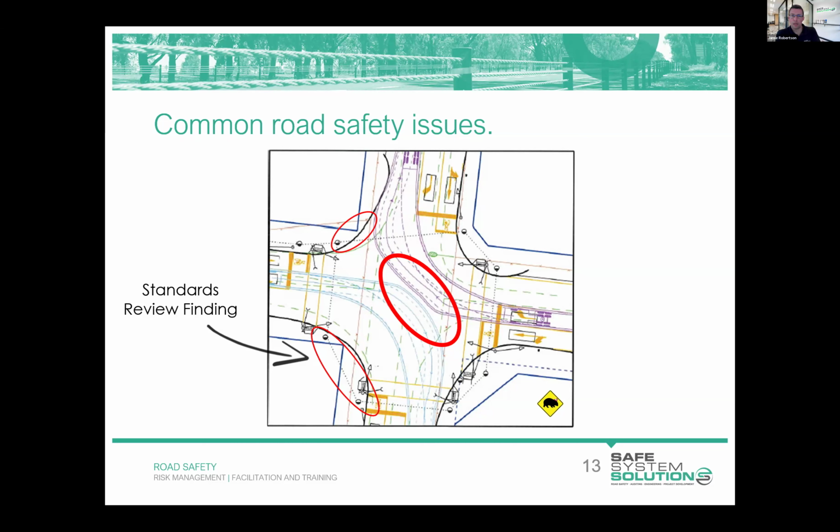It might even encroach a curb or an island, and that might influence the placement of roadside furniture, and we might look to pave behind curbs and things like that, but we don't expect that vehicle will remain on the pavement necessarily. It's a vehicle that will come along very infrequently. It might even come along under traffic management, so the risk associated with that vehicle movement is low. So we accept, we make some compromises.